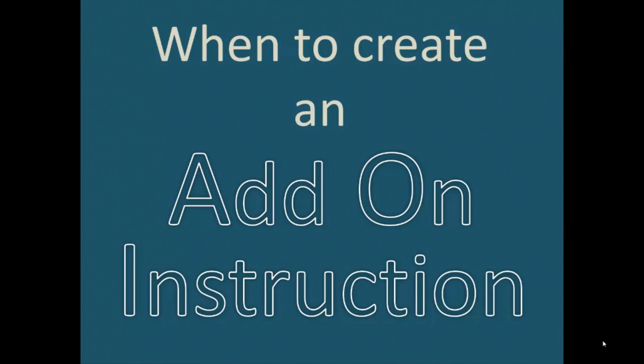Add-on instructions are best at providing a specific type of functionality or device control. If you work in this industry a lot, you will see a lot of abuse of add-on instructions. A high level of convolution, very difficult to follow, especially trying to troubleshoot backwards from an output that's not coming on.